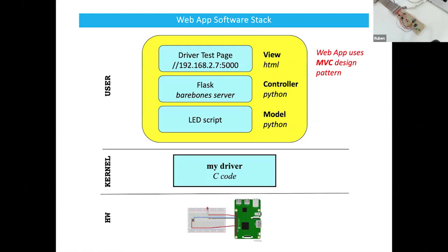So there are techniques you can use to make sure that, for example, when an interrupt is going on, it's accessing the GPIO registers, nothing else is going to access those registers at the same time. Or when the user process is accessing the registers, it's got exclusive access and nothing else is accessing those registers as well. And all of that sort of synchronization has to be handled by the driver, essentially.